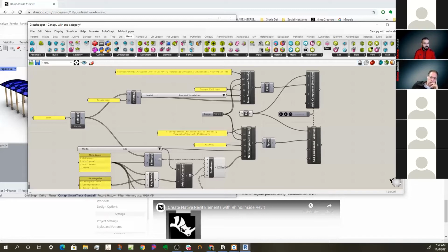So walls are a good example. Walls have a lot of hard-coded properties, parameters. So they have a center line, let's say. Let's just simplify the idea of what they are just to even talk about it. They have a center line, and based on that center line you create a wall, and the wall has height, and it has a width and material and layers, and all those things. And you can think about everything beyond just that center line. Everything is a parameter on that wall, as a wall style, and that style has a bunch of characteristics.